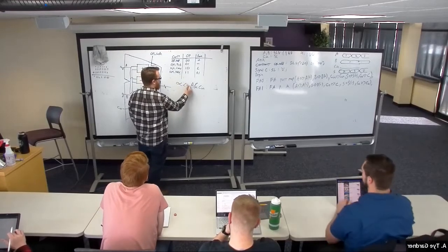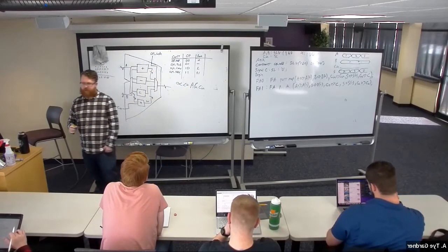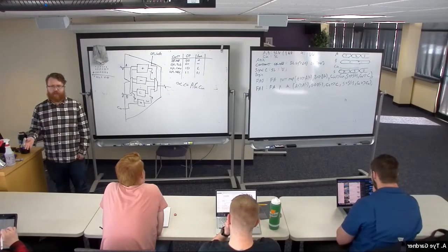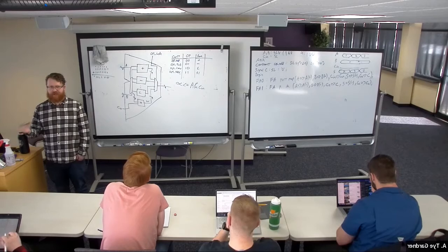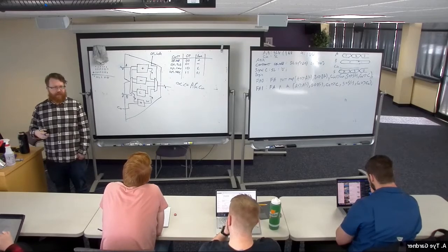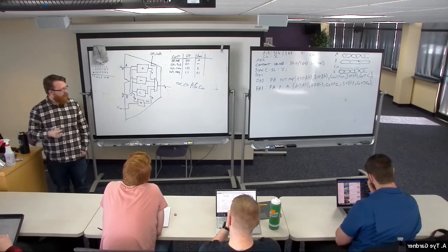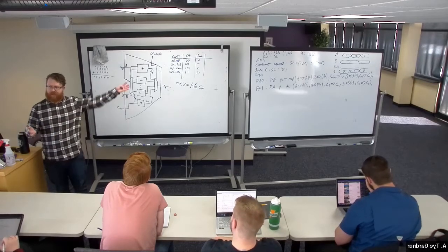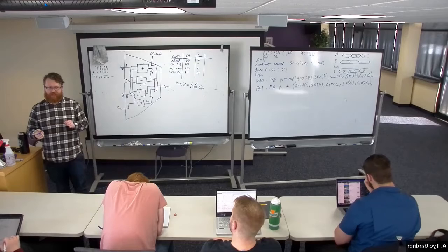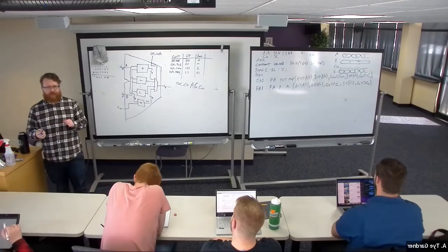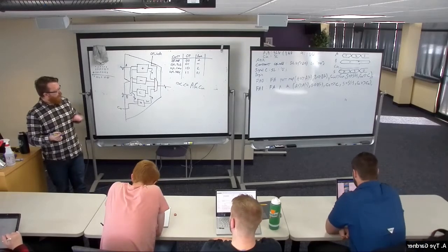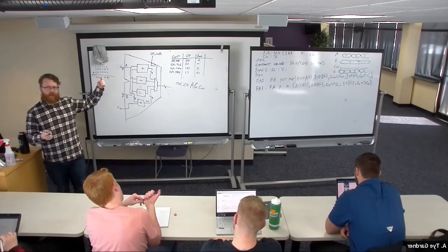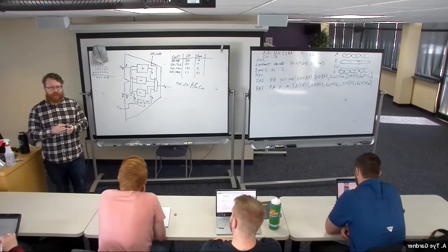Alpha gets assigned A ampersand Cn. Ampersand concatenates is the word, which means take two things, stick them together. In that case, alpha is 9 bits, A is 8, Cn is 1, 8 plus 1 is 9. This is fine. It will concatenate just fine. Probably that's going to stick Cn on the end of A. I probably want to go the other way, but we'd have to think about it a little bit.